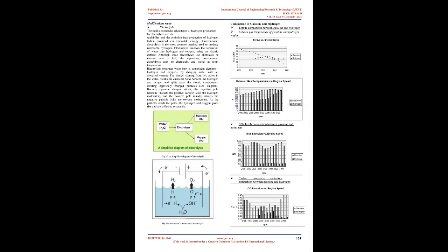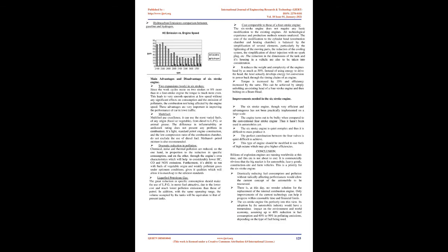Bajulaz 6-stroke engine. Design and construction. The engine consists of 4 valves: intake valve, 1, heating chamber valve, 2, combustion chamber valve, 3, and the exhaust valve, 4, which control the flow of the fluids in the cycle. The engine has a combustion chamber for burning of fuel-air mixture, 6, which is completely isolated from the cylinder, and the burning of the fuel has no direct effect on the piston as in the case of a 4-stroke IC engine. An air heating chamber surrounds the combustion chamber which holds pure air under high pressure.